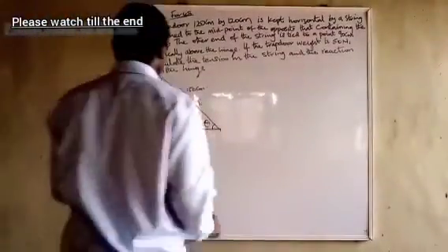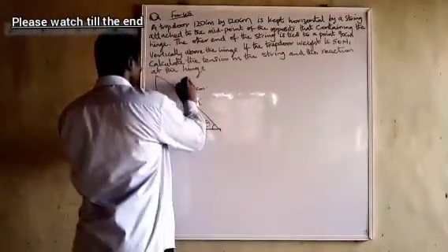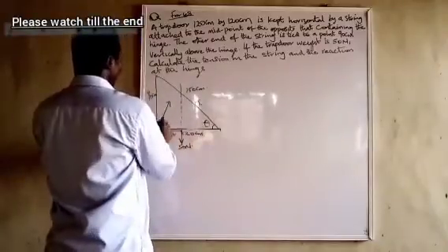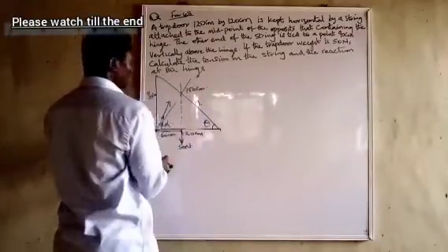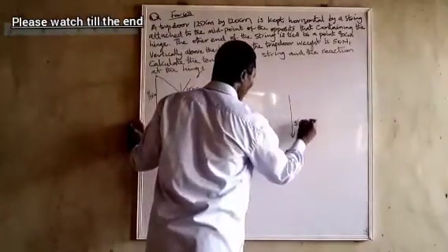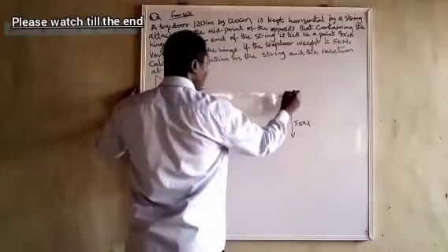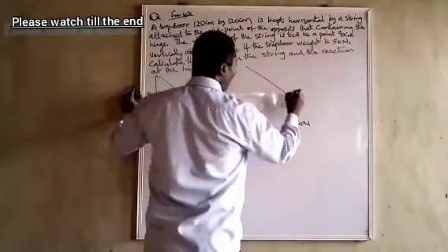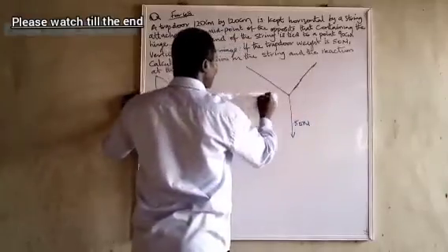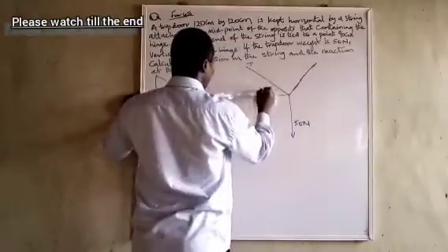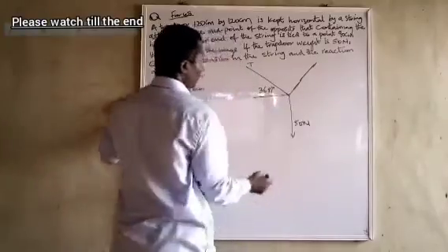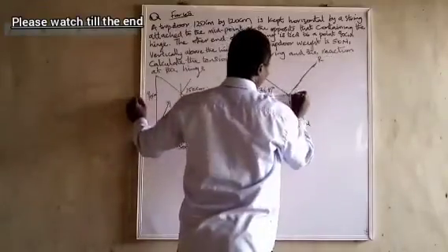Now you can see, look at it. So with this, I can find theta, and then R must pass through this place. So if I should draw it now, I have 50 Newton, T, R, and T is at 36.87 degrees. R is here.